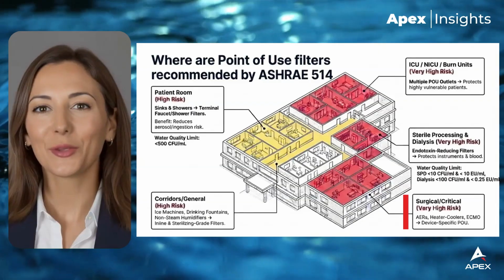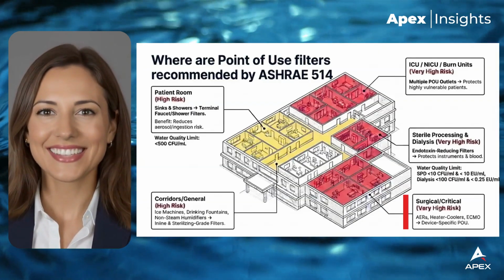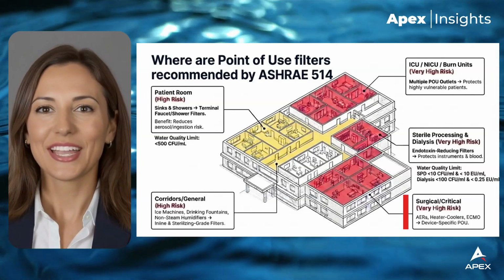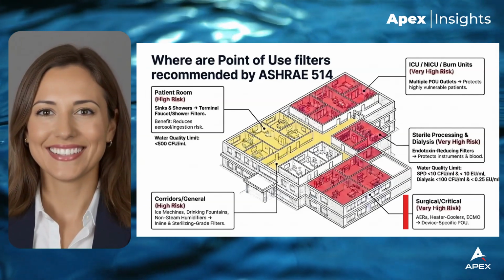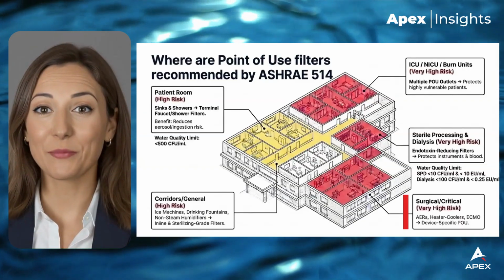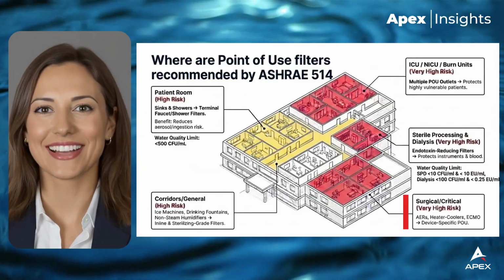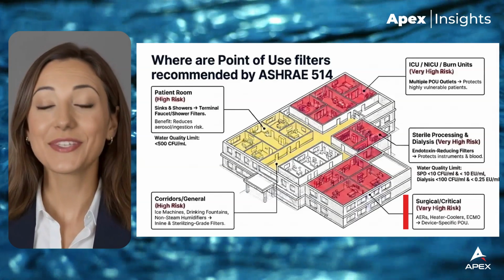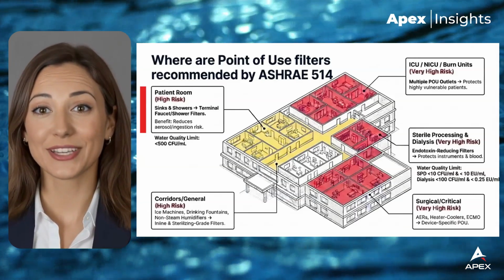In surgical and critical care environments, devices like endoscope reprocessors, heater coolers, and ECMO systems introduce direct exposure pathways. These require device-specific point-of-use filtration, designed to meet both microbiological and performance standards. Water quality target is near zero bacterial levels, with device-specific performance and sterility requirements.